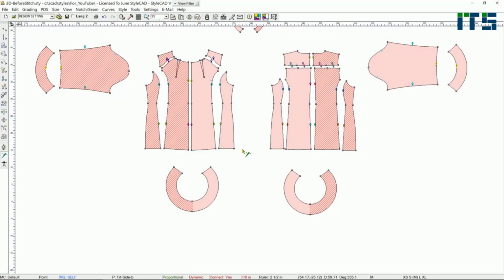Here is an example where two sections are stitched onto a single section. We select all three sections and then drag from the multiple section side to the single section side. The single section is proportionately divided to match the multiple sections. By moving the cursor over the stitch symbol, we can view the stitching lines.